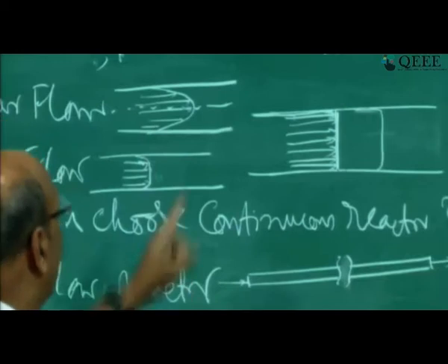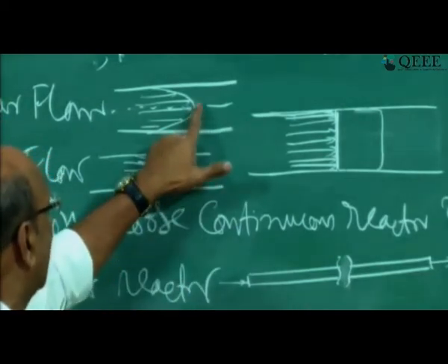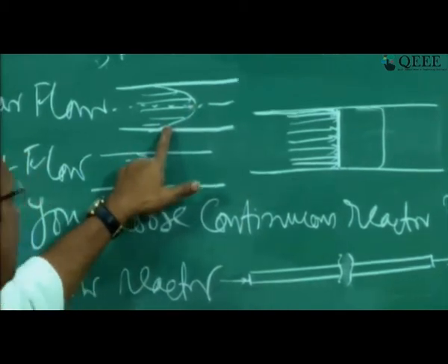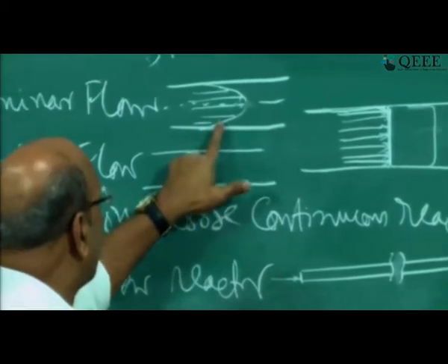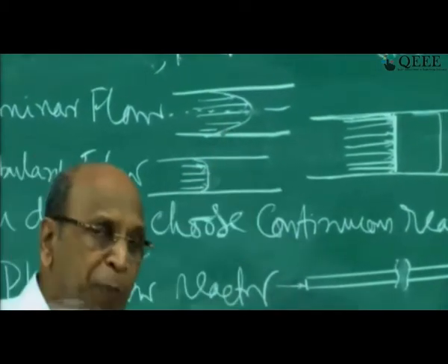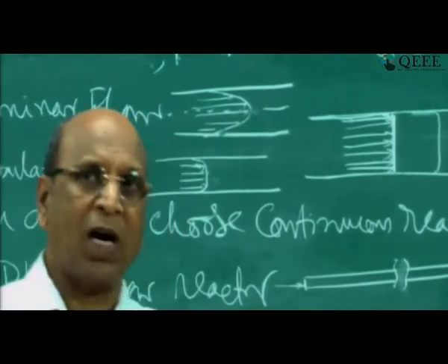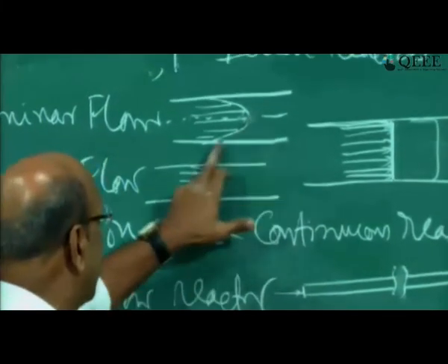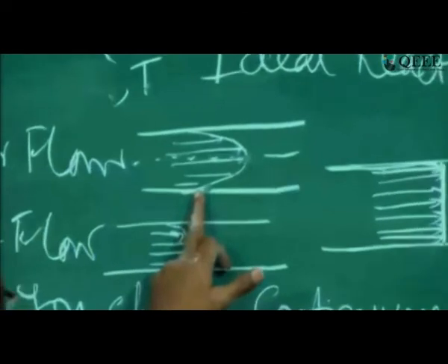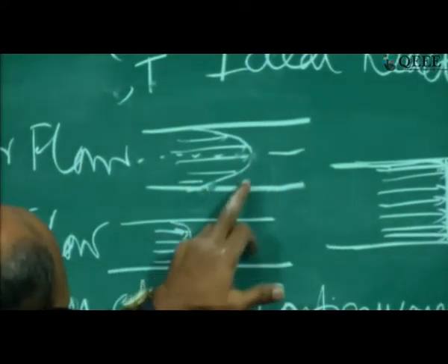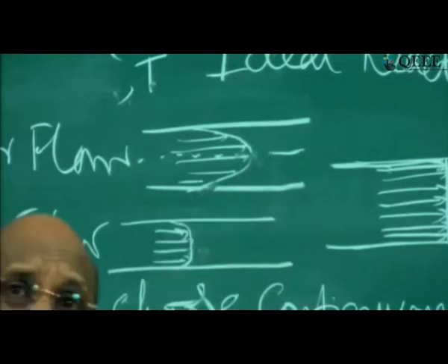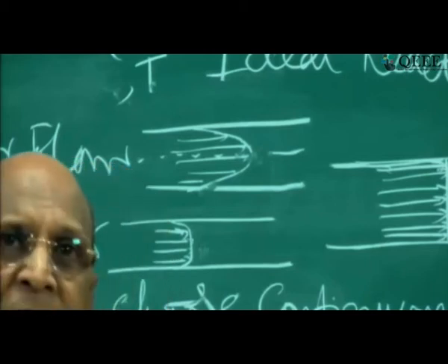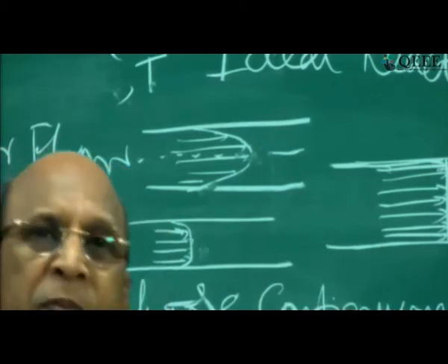That is not possible if I have laminar flow. We know from fluid mechanics, the particle here moves much faster than the particle here. So, the residence time of this is smaller when compared to the residence time of the other particle. They are not spending same time. Please recall your fluid mechanics. At the center, you will have the fastest moving particle. On the surface, you have zero velocity, I mean, if you assume no slip condition. So, in between you have residence times of those molecules or particles changing continuously. So, that is why laminar flow is not plug flow.